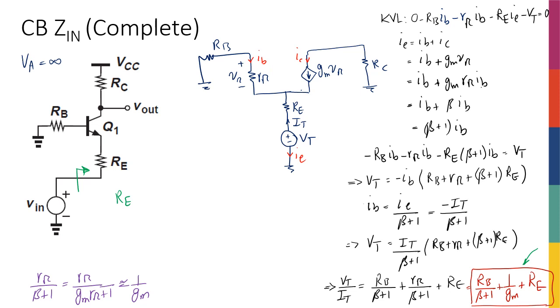So that was something that we expected, plus, so it almost feels like this RE is in series with some stuff. So what is that stuff? Let's call it whatever we see from here up, right? So like RE in series with whatever is up there. I know that looking up into the emitter, I'm going to have some 1 over GM. Great. So I got the second component.